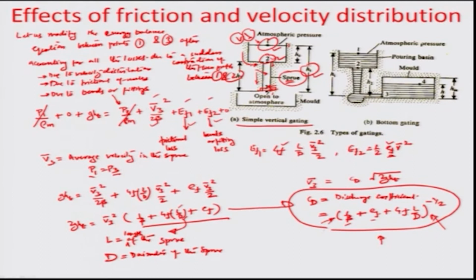So, the earliest assumption that you can make, if there is no loss factor, that is C_D equal to 1, is that V3 converges to root of 2 g H_T, which is in fact the same term as you had seen in the analysis where we neglected the frictional effects.